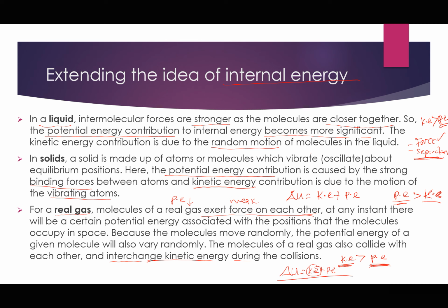For an ideal gas, the molecules are considered to be infinitely far from each other, so the intermolecular forces of attraction or repulsion are completely negligible. If these forces are negligible, it implies that the potential energy contribution to internal energy boils down to zero. Therefore, for an ideal gas, potential energy becomes zero since the force between the molecules is approximately zero, that is negligible.